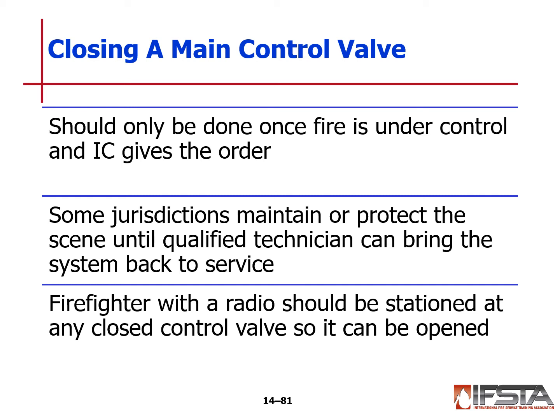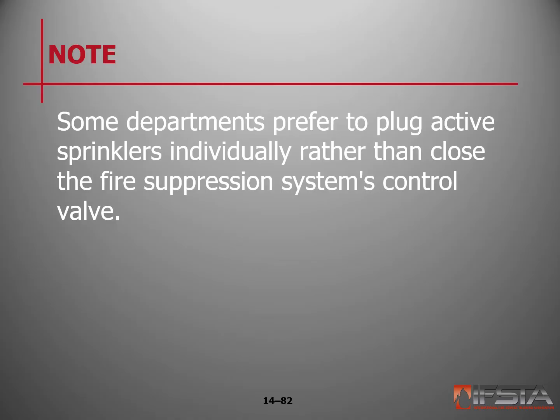Closing the main valve should only be done once the fire again is under control and the incident commander gives that order. Some jurisdictions maintain or protect the scene until a qualified technician arrives and can bring the system back to service. Firefighters with a radio should be stationed at any closed control valve so that it can be reopened.